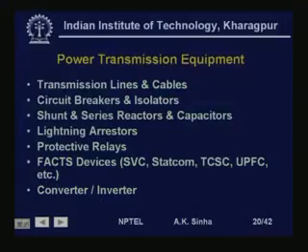The basic idea is that if lightning strikes a transmission line, a surge voltage, which is a very high voltage and current surge, propagates on the transmission line, and these need to be grounded or isolated and not allowed to go up to the equipment where they can damage the insulation of the equipment. So, we use these lightning arrestors to ground these surges.